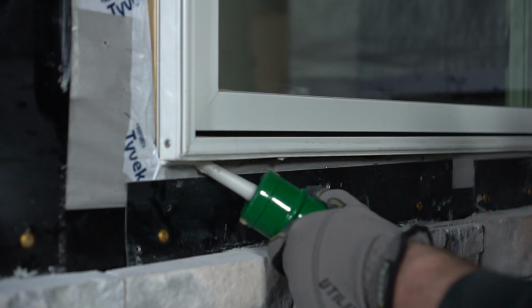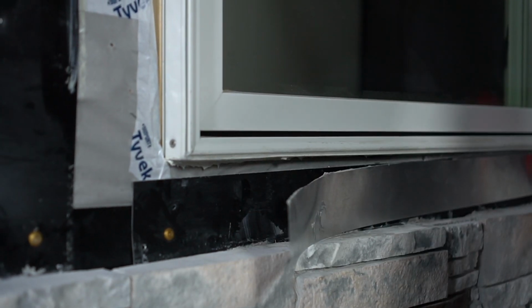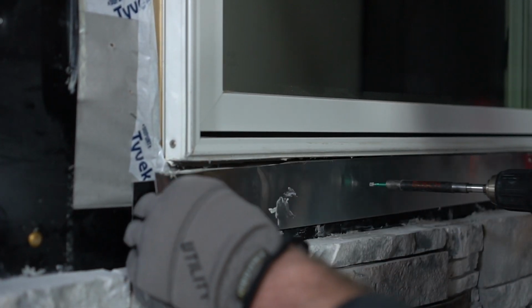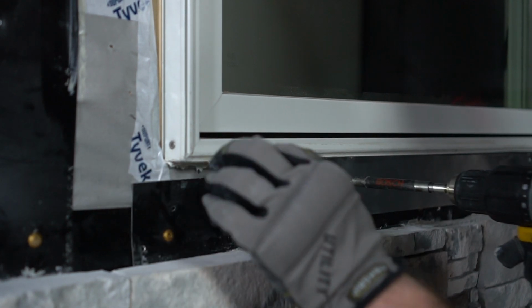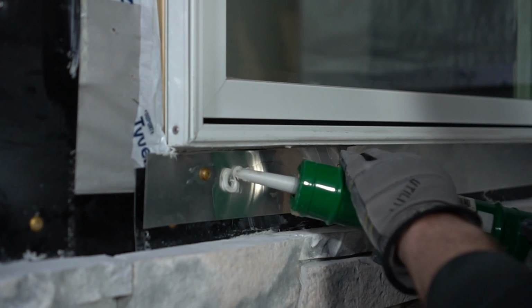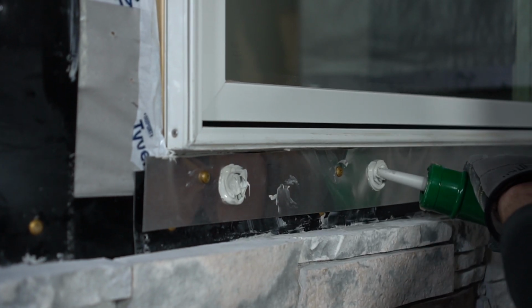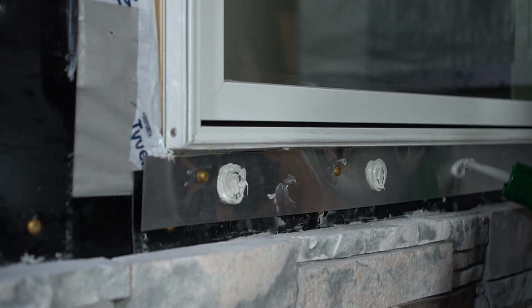Apply a bead of bedding sealant where the bottom of the opening meets the sheathing. Bed the top edge of supplemental unpainted aluminum flashing into sealant and fasten securely with Silvermine's approved application screws. Leave a 3/8" gap between sill and window frame. Apply 3/8" thick quarter-size dollops of construction adhesive every 6 to 8 inches to the aluminum flashing behind the sill.